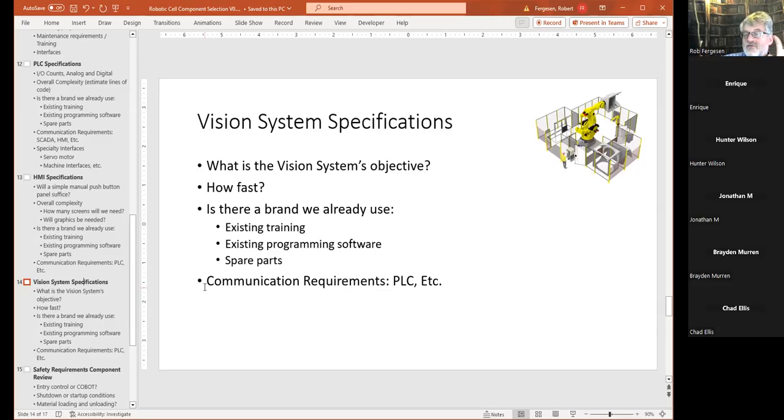Now that third criteria, that third situation, is probably the most complex. If you hand a robot a pile of parts in any random orientation and you rely on the vision system to tell that robot exactly where it is and its orientation, that's the most complex thing. Now you need an expert in the vision system area as well as an expert in how the robot gets that data, applies it, and moves. So it's a very complex scenario. And there's more than that.